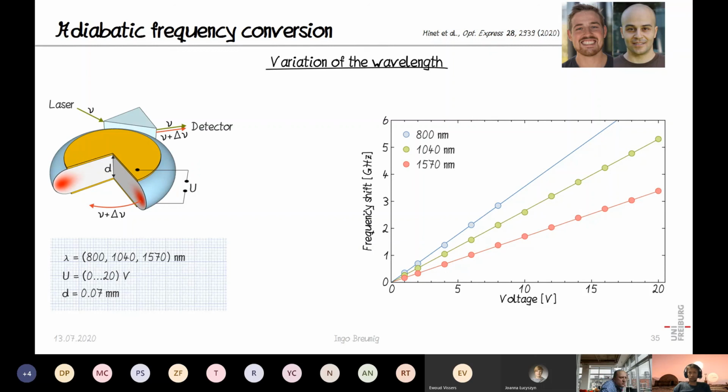Would it be possible to fabricate Chi2 resonators on chip? Yes, of course it is. There are several groups doing it. There are very, very good results on resonators made of lithium niobate with quality factors up to 10 to the power of 7. There is Paul Seidler from our consortium doing very nice stuff in gallium phosphide. I guess the quality factors are also beyond 10 to the power of 6 at least. I guess also approaching 10 to the power of 7.